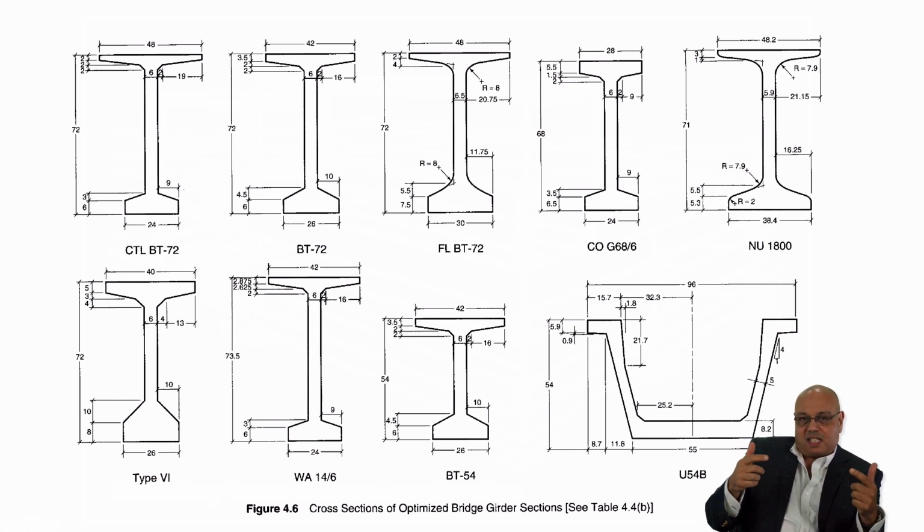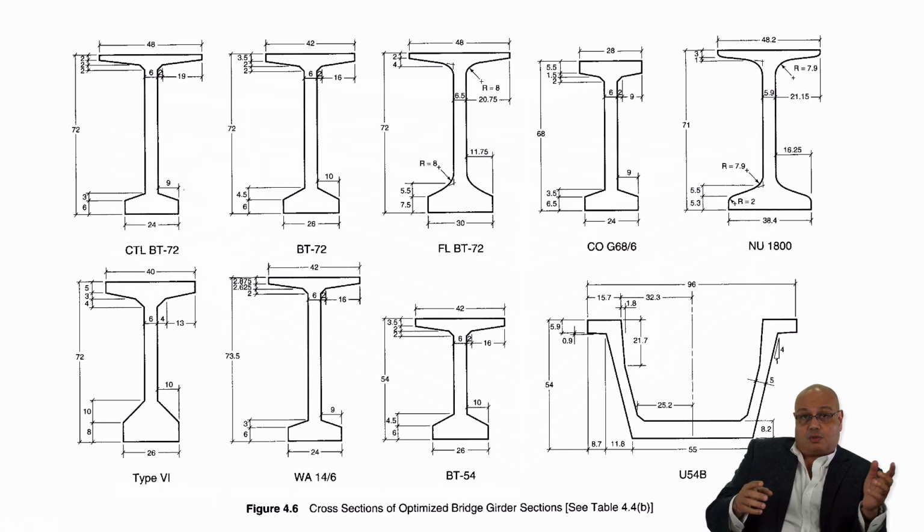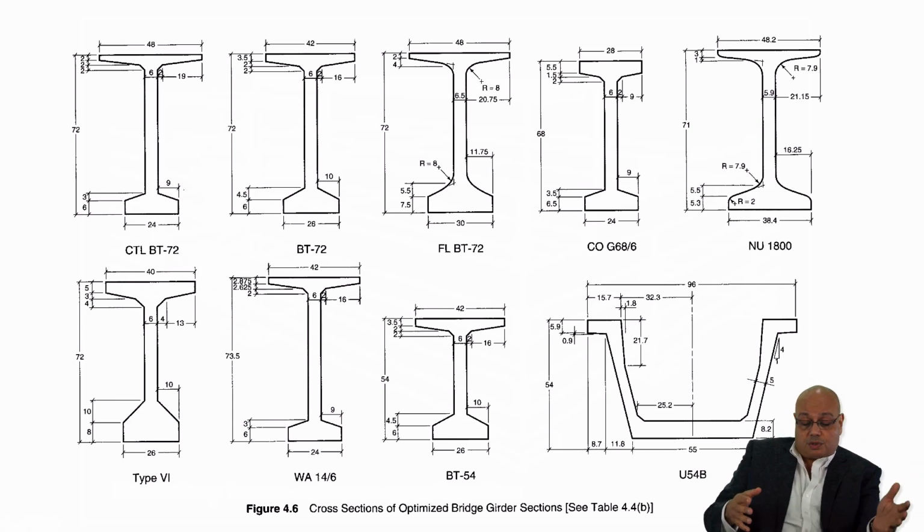We're going to be discussing how you can have bigger lengths for prestressed concrete. For reinforced concrete, for a bridge for instance, you cannot exceed like 50 feet or so. In prestressed concrete, you can get to 120, 130 feet and more. And it's going to have a shallower cross-section as well, for a reason.